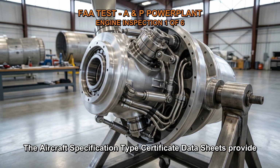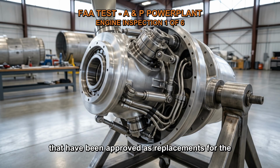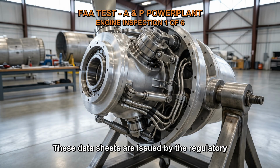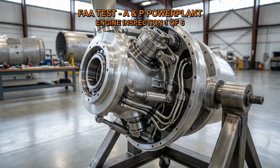The aircraft specification type certificate data sheets provide the necessary information to identify alternative propeller models that have been approved as replacements for the damaged propeller. These data sheets are issued by the regulatory authorities and outline the approved configurations and components for the aircraft.